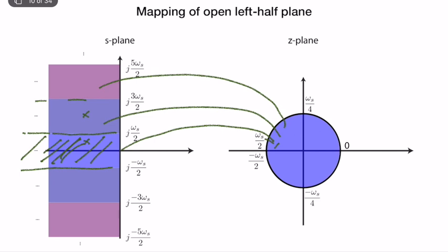Okay, so if you have frequencies in your plant, the frequency components, it's general to increase your sampling frequency such that all of your poles stay inside the primary strip, such that you kind of know that at least your mapping is some sort of unique. It's not unique, but you know that this maps to this. But this is also mapped to that, but it's a very high frequency component, but it doesn't look like a high frequency component in the Z domain. So we try to stay here in terms of our design of the plant and digital control system.